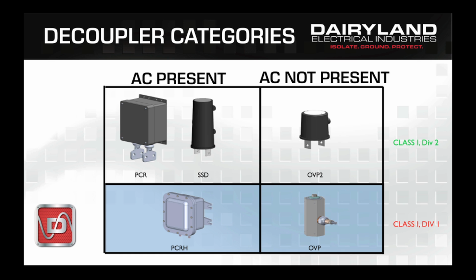If your installation is a remote location and you're not located close to a power line, it's not unusual to have no AC present, but in most urban settings or where a pipeline parallels overhead power lines, generally there will be some AC present. The presence of AC can easily be verified with a simple handheld meter by measuring AC potential from pipe to soil.